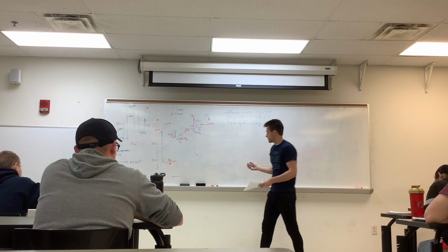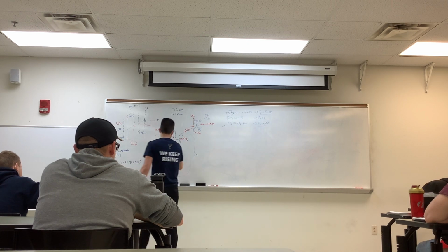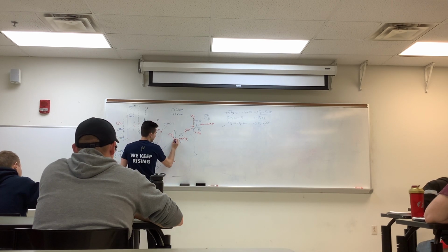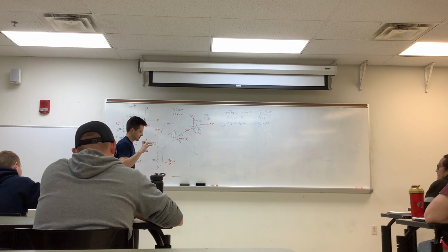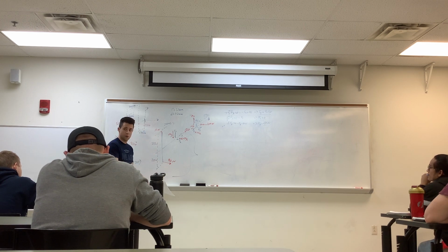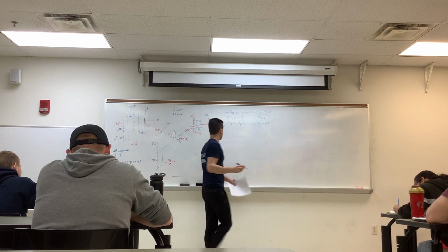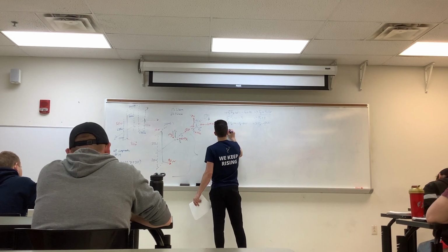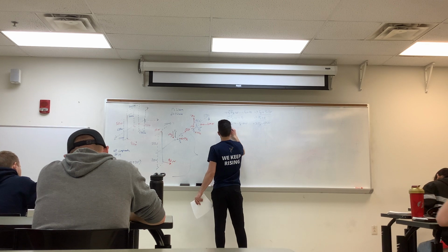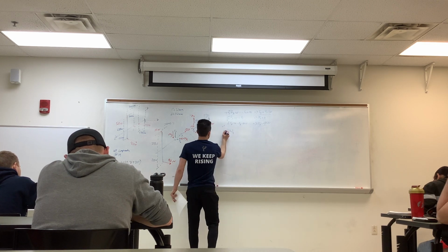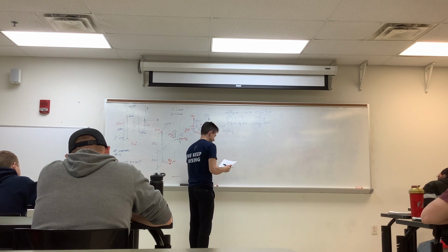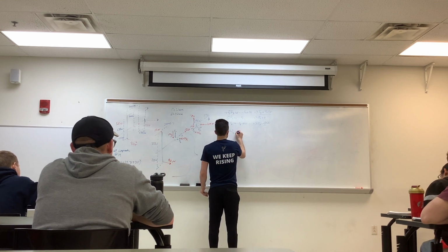Next, we can do our moments. As I do with a lot of these, I'm going to take it about the centroid of that cross section, or the center of it, as a point O. So, point O. I'm going to sum the moments at point O about the x-axis. I'm going to do the right as positive. All of that is equal to 0.